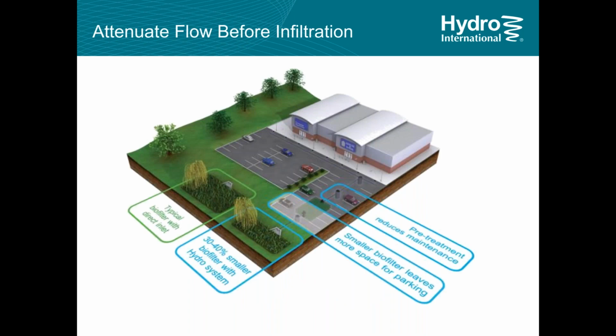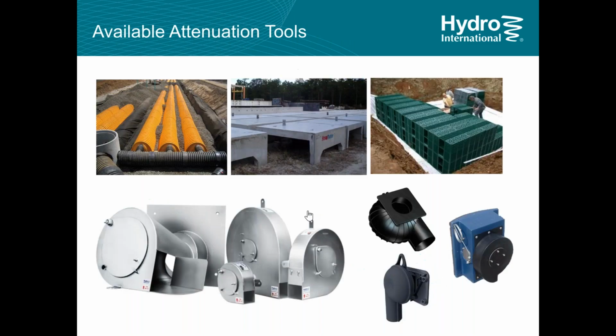One way that people deal with this is to essentially decouple their water storage from their water infiltration. And if possible, arrange it so that they're storing their water upstream of their infiltration system, underground where you can park on top of it, essentially. And so here's an example with some attenuation upstream of a bioretention system. So this is storage under parking.